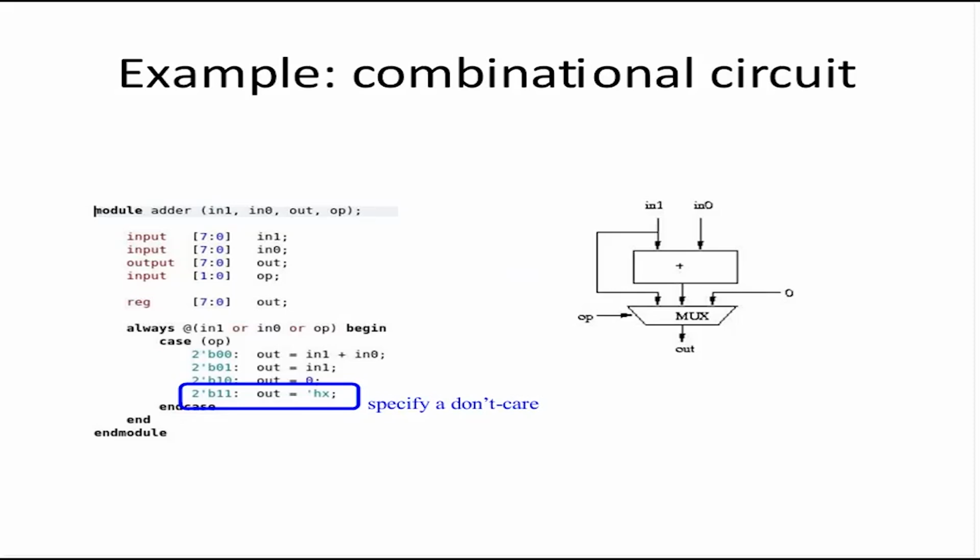Like in a truth table or a Karnaugh map, for don't care conditions you could make those conditions 0 or 1 depending on what gives the lowest amount of hardware. It's exactly the same for Design Compiler. It will see which option on out results in the lowest area, and it will use that.